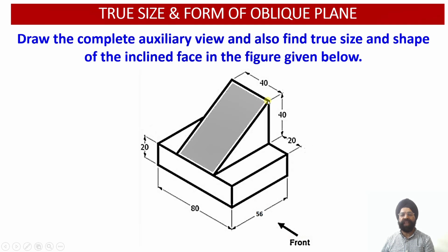of the orthographic projection. While we are looking at the solid from the top side, that is from above, the view which will be obtained onto the horizontal plane will show us the shortened view or the reduced view of this particular cut section. The reason is that this cut section surface is inclined to the horizontal plane, so the projection of this cut section surface onto the horizontal plane, obtained in the top view projection, will appear as an apparent shape of this section.